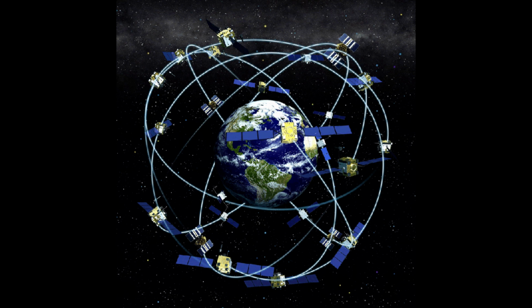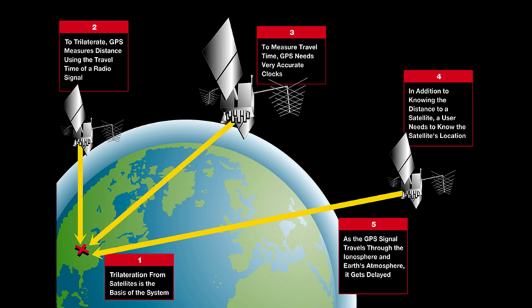A GPS receiver must be locked onto the signal of at least 3 satellites to calculate a two-dimensional position, latitude and longitude, and track movement. With 4 or more satellites in view, the receiver can determine the user's 3-dimensional position, latitude, longitude, and altitude. Other satellites must also be in view to offset signal loss and signal ambiguity. The use of the GPS is discussed in more detail in Chapter 17, Navigation. Additionally, GPS is discussed in the Aeronautical Information Manual, AIM.